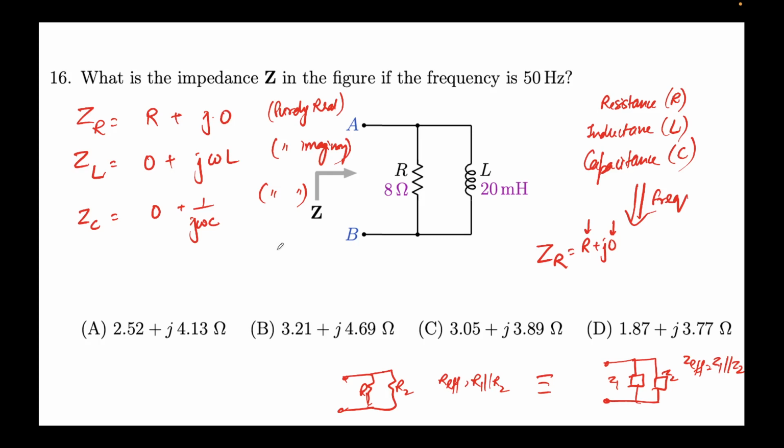So a better way to solve it on paper or from software is to convert everything to the frequency domain. And if we use this impedance scheme that we have over here, then it becomes very straightforward to solve the problems, because essentially now we will be treating everything just like we did in the DC domain. So the AC domain gets an analytical counterpart in the DC nodal analysis, and accordingly also the Thevenin and the Norton analysis that we had talked about.